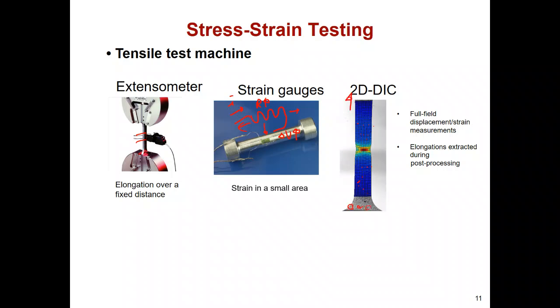Then when you pull this solid specimen, you can track how much each black dot moves. From the contour plot, you can see how far the black dots moved. With just a high-resolution camera, and a solid structure with dots detectable by that camera, you can easily detect the strain field.